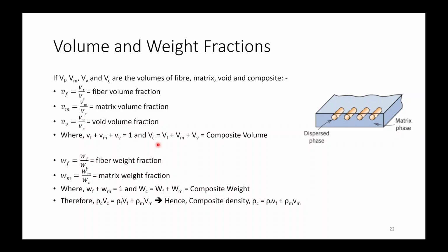Now, the volume of composite will be equal to the volumes of fiber, matrix and voids. In the case of weight, the weight fraction will be similar to these, and the weight of composite will be equal to the weight of fiber plus the weight of matrix, and the fractions will add up to 1.